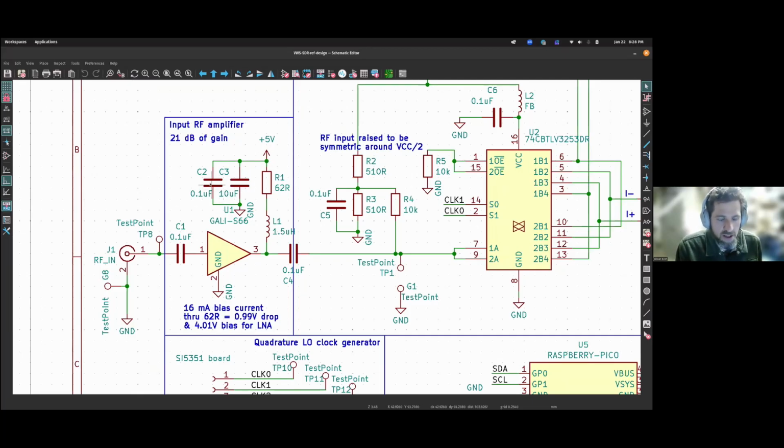So it's a good practice to have these decoupling capacitors as close to the component as makes sense. You don't want them to be a long way away because it's the inductive losses along the conductor between these capacitors and the component that's consuming that current. Those inductive losses can lead to basically generating noise on your power traces and your ground lines.